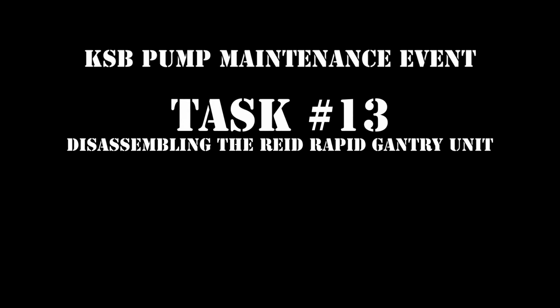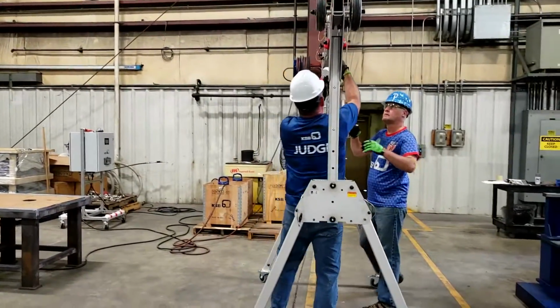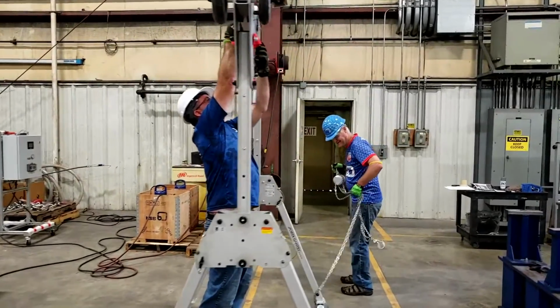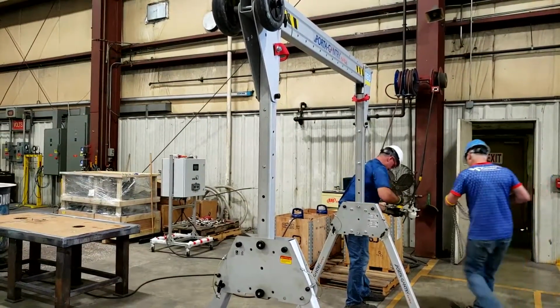KSB Pump Maintenance Event Task 13. Disassembling the Reid Rapid Gantry Unit. You will remove the trolley and the chain hoist. After removal, reinsert pins in the trolley just as it was during the start of the event. The pins shall be inserted on the same side as they are attached to the trolley.